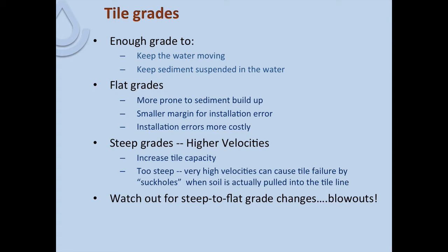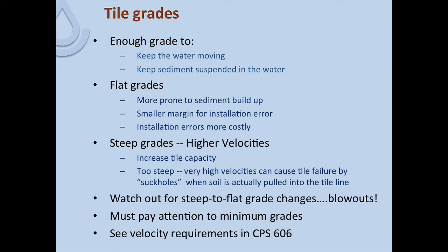We need to pay attention to minimum grades, again, to make sure that we got enough water velocity to keep that sediment suspended. And so again, refer you to Conservation Practice Standard 606 for velocity requirements.